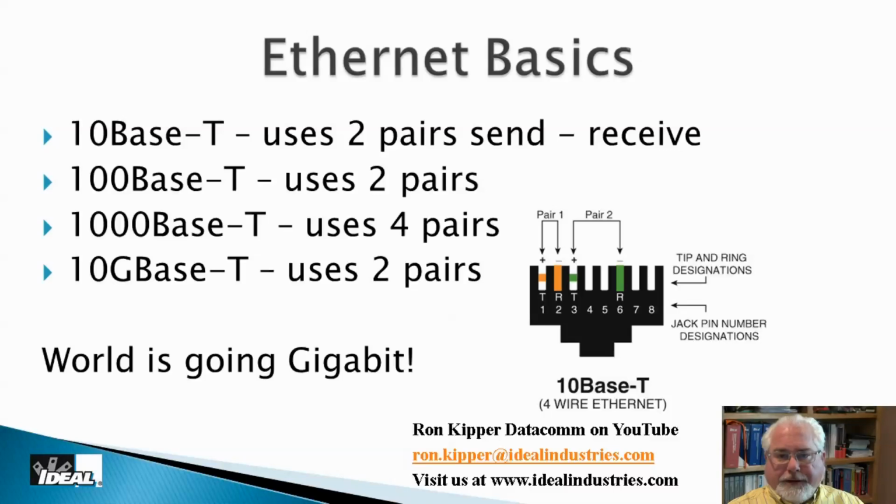If you look at Ethernet today, and virtually all networks in the world run Ethernet, probably 90+% of all networks, including the internet, you'll find in 10 and 100 base T data networks, which are very common in the industry, and again, think about how fast your high-speed internet line coming in from a cable company actually is, which is usually somewhere in that range, they only actually use 2 of the 4 pairs to make that work. Pins 1 and 2 are a transmit pair, and pins 3 and 6 are a receive pair. And so the computers are not using all the pairs in the cable.